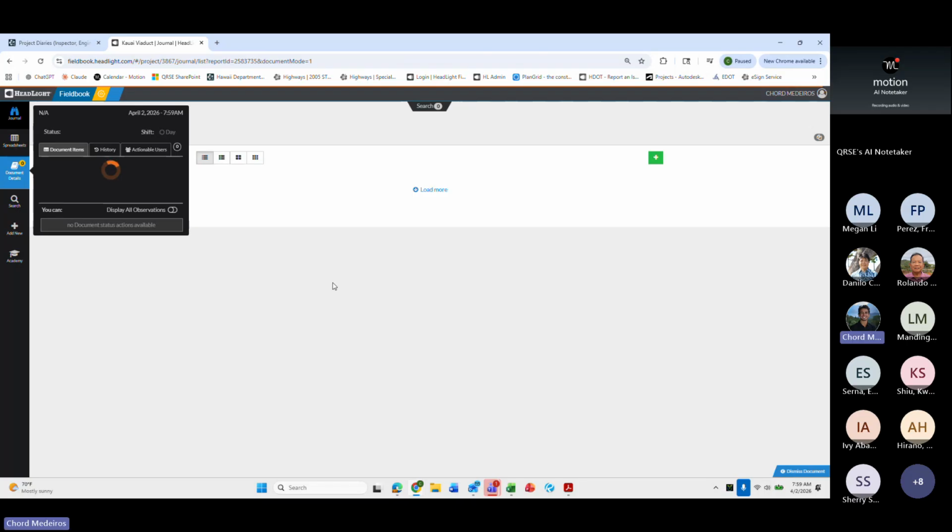We need to make sure that that work is verified, because later on down the road, if all these diaries are left in the submitted phase and it's 4, 5, 6 months later, and you go back, you want to change a diary, you can change it, but you can't really tell the contractor to do anything at that point. It's too late, right? In most cases. So we need to be sure that we are properly reviewing these diaries and these submissions in a timely manner.